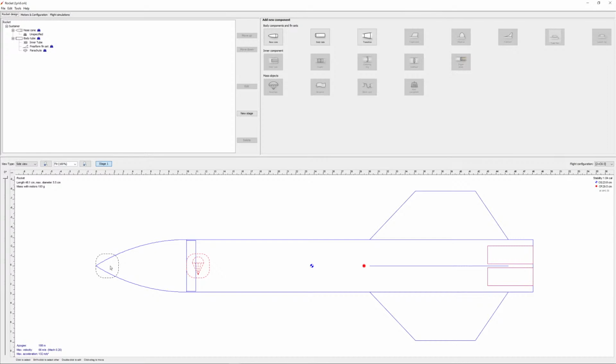So what we had to do to prevent that is put in, you can see this little dashed line, that's representative of a mass of 72 grams up at the top of the rocket. The benefit that brought to us was that instead of balancing a pencil, it's more like balancing a bottle of hand sanitizer or something like that, where it's a lot more stable to balance.